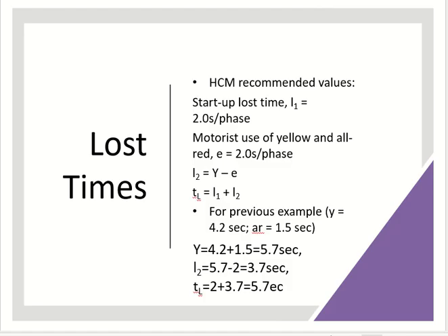So for example, in this example, you calculated yellow time to be 3.9. Obviously, you will not design 3.9. You will design 4. So from the 4 seconds of total yellow, the usable seconds are 2, and the remaining goes under clearance loss time. Clearance loss time is the remaining part of yellow after 2 seconds, plus all red time.